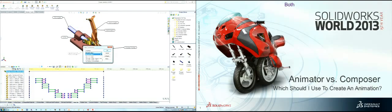What'd SolidWorks do with it? Well, SolidWorks didn't do anything with it because it doesn't load it there, but we have a lot of 64-bit computers running around now. Codecs are either 64-bit or 32-bit. This is a 64-bit machine, you're only seeing the 64-bit codecs. When I play it back, all the players are 32-bit. So when you download codecs, you need to make sure you get both a 32 and a 64-bit because 64-bit SolidWorks can use a 64-bit to compress. Windows Media Player needs a 32-bit codec to decompress.